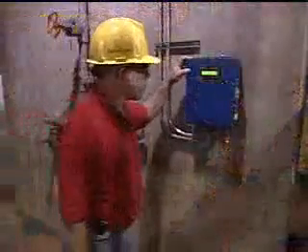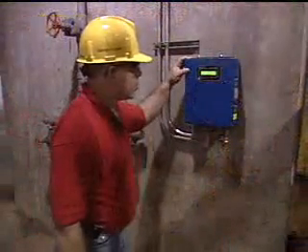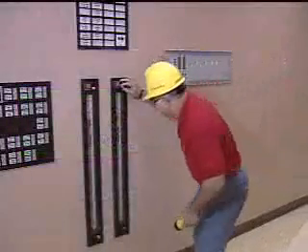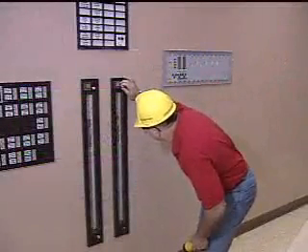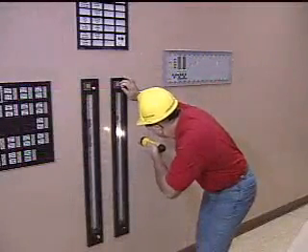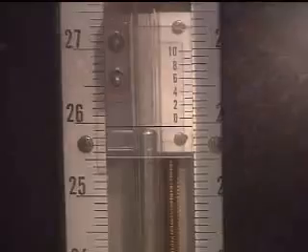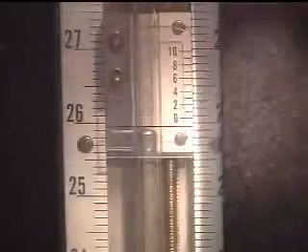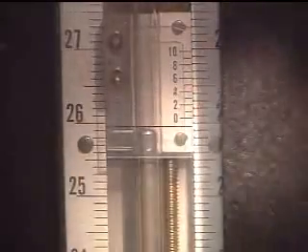Operators also routinely check the airflow gauges and monitors in the air removal system. Abnormally high readings could indicate an air leak into the condenser. In many plants, operators monitor condenser vacuum by checking manometers that are located in the control room. The manometers indicate whether condenser vacuum is in the proper range for the operating conditions.